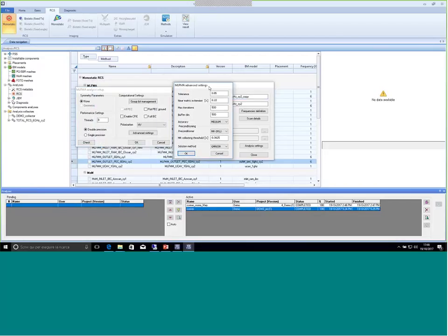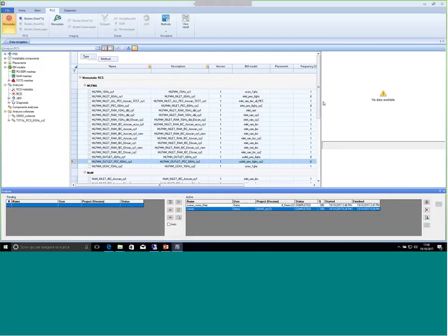For the multilevel fast multipole method, there are all the typical settings. Here, the tolerance of the iterative method, near matrix extension. Since it is an iterative method, if we start from a well-conditioned problem, the simulation is going to be faster, so we have some preconditioner. And also we can choose the solution method for this simulation. All these parameters must be tuned based on the specific target that I'm analyzing. So that was an application example of the multi-method approach and also of the decoupling procedure.